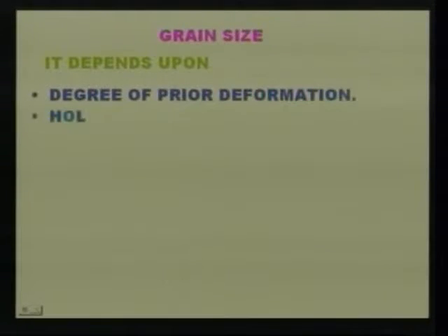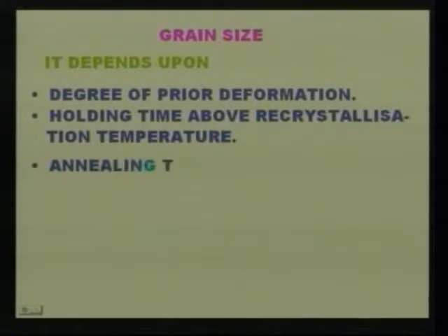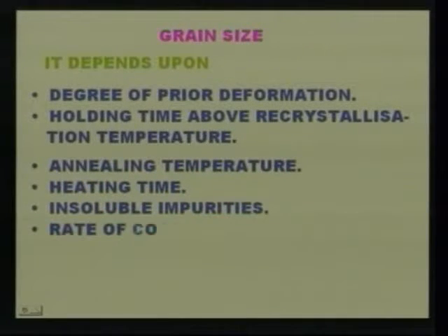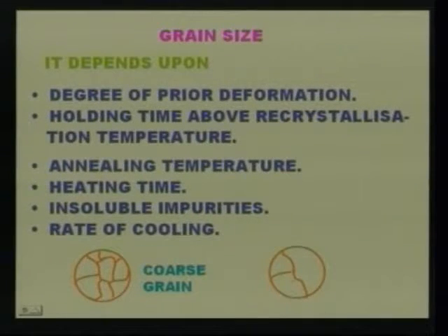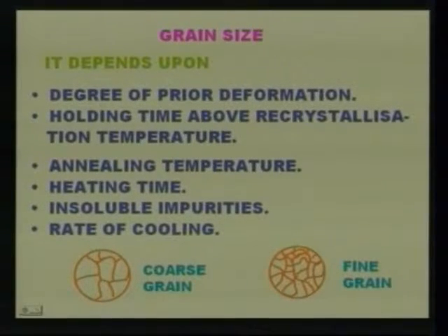Now, let us see the grain size after recrystallization. It depends upon the degree of prior deformation and the holding time above the recrystallization temperature. It depends on annealing temperature, heating time, insoluble impurities, and the rate of cooling.